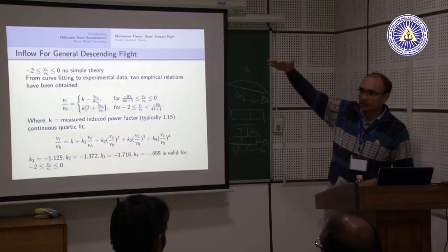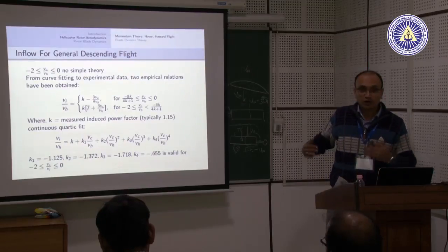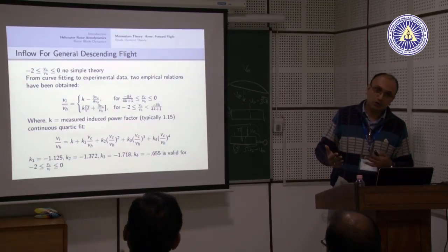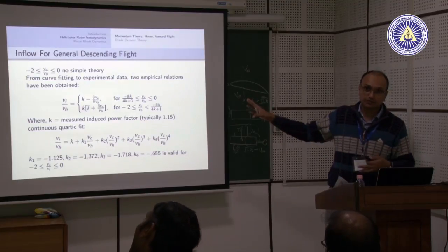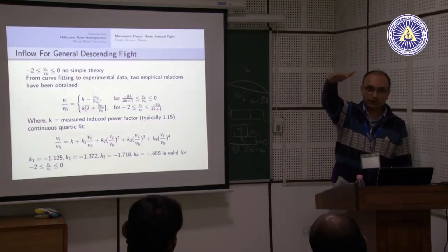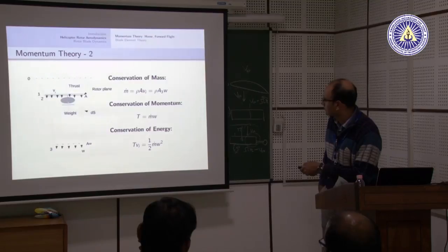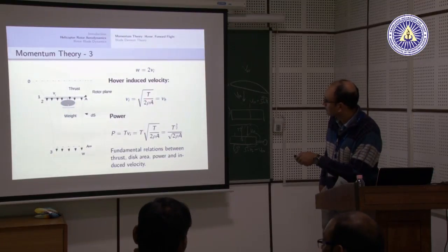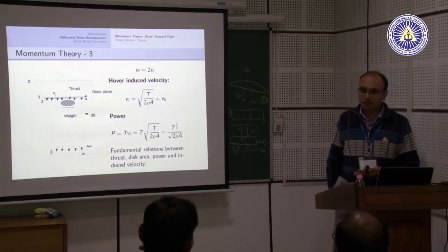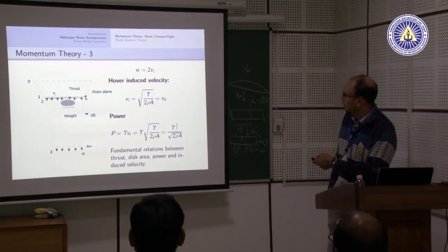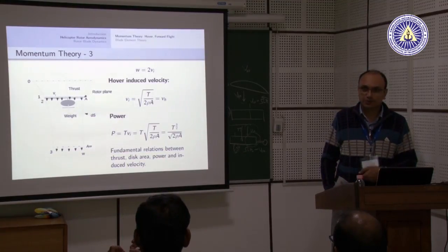So when you are descending at low, controllable velocities, normally you never want to descend at velocities more than 0.1 or 0.15 of the hover induced velocity. If you know the weight of the vehicle, let me go back here. For all these formulas we saw, what is this T actually? When you are hovering, this is the same as the weight of the helicopter, right. So if I know the weight of the helicopter, I can very easily find out what my induced velocity Vi and Vh are.